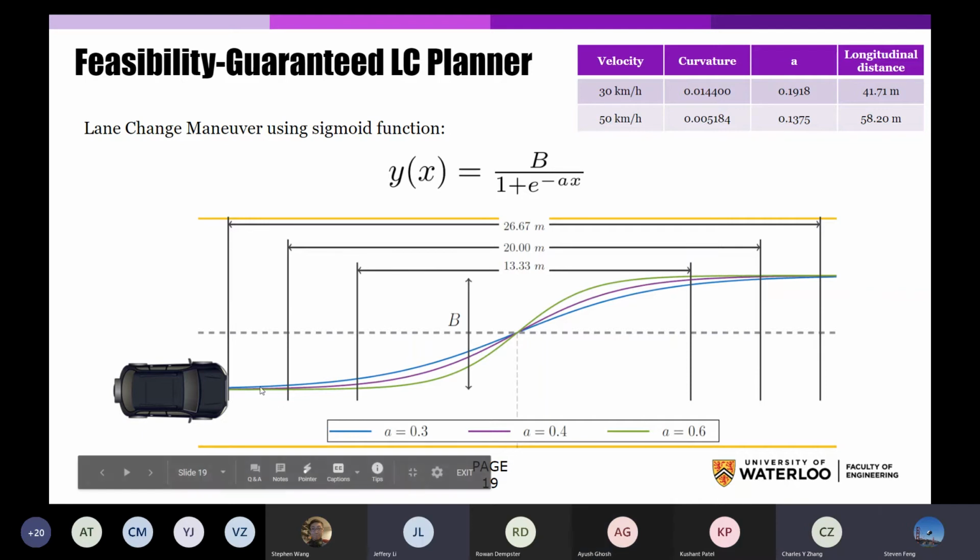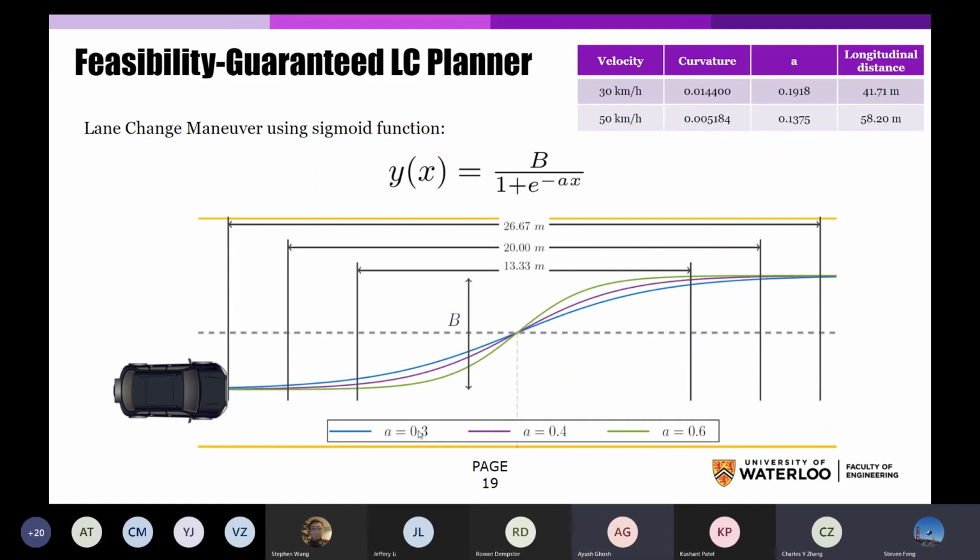It's the distance along the road. So you have longitudinal and lateral distance. If you're going around a turn, using Euclidean distance won't be very good, because the road moves. But if I just care about the distance along the road, which is curvy, or the distance I am away from the road, which is curvy, the first being longitudinal distance, the second being lateral distance, then it's like not caring about whether the road turns or not. Yeah, you're ignoring the road geometry. Okay, got it.